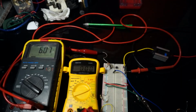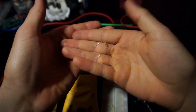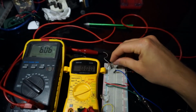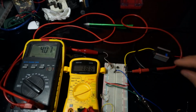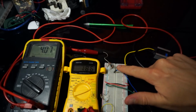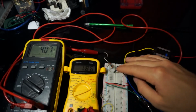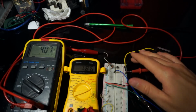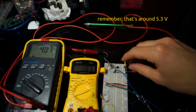Okay, now I'm going to move us up to a 2.2 kilo ohm, and that should already get us close to, maybe it'll even already get us to the rail. Okay, so we're at 4 volts on the collector, and that is not enough to push this transistor out of saturation, so that's a good thing. You can see that is confirmed by the fact that we're still at 1.86.